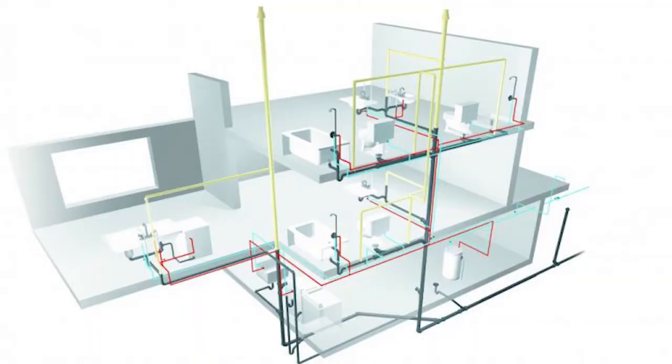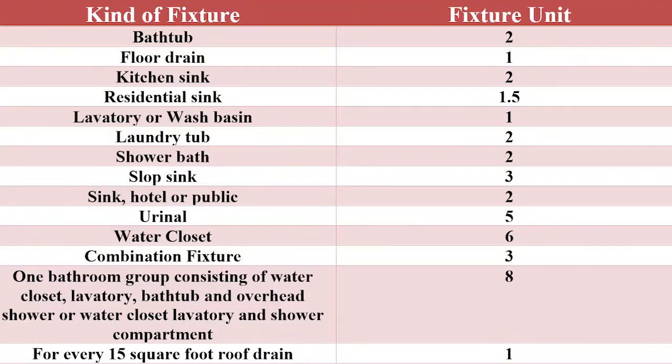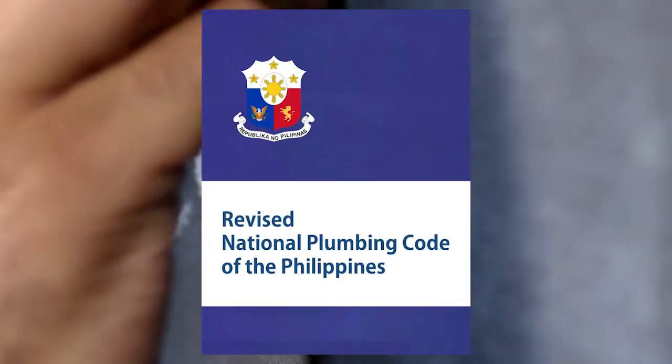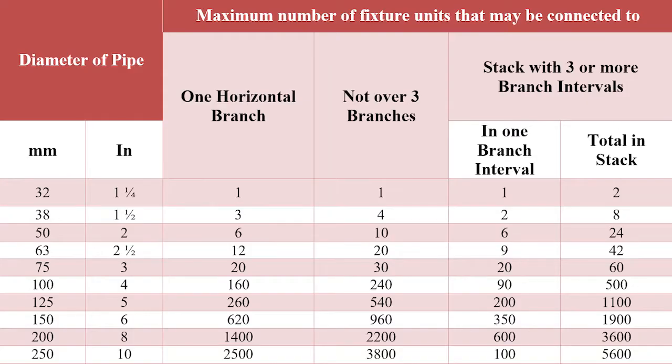Plumbing design, particularly the sizing of the pipe, should be determined by way of mathematical computation using the fixture unit values. However, regardless of the results, when it is smaller than what is promulgated by the Plumbing Code as presented in the tables, the code must prevail.